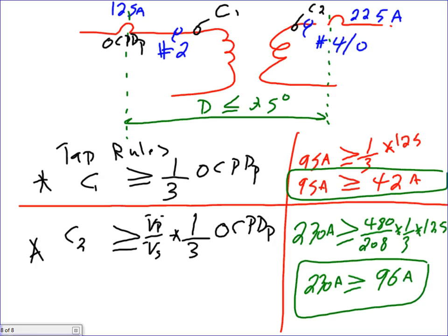285, go down on the overcurrent protection device. What's the 285? 250, down. I could have easily, based on the tap rules, put 250 amp right in here, no problem, if I stay within that 25 feet. Why it's important? Because if you put 125 and every time you energize your transformer you trip because of inrush in the transformer, the tap rules solve this problem for you, just based on the conductor size that you did, strictly on 95.